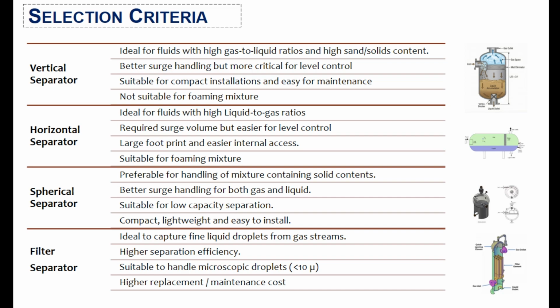While spherical separators are preferable for those mixtures that contain solid contents, and they have better surge handling capability for both gas and liquid. Spherical separators are suitable for low capacity separation. They are compact, lightweight, and easy to install.